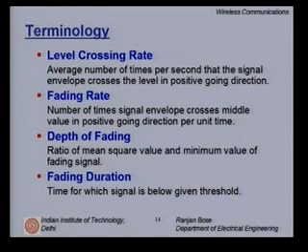All right. Also, please remember we had earlier talked about handoffs. Handoffs occur from one base station to another base station when the signal of one base station drops beyond a certain threshold, whereas I start receiving signals from the other base station. At that time, we hand off. However, if my fading duration is large and I have large depths of fading, then chances are that I will hand off not because I am close to the edge of the cell and I am moving to the new cell, but because I am sitting in a fade. What has to be avoided is that we should not hand off because of fading.